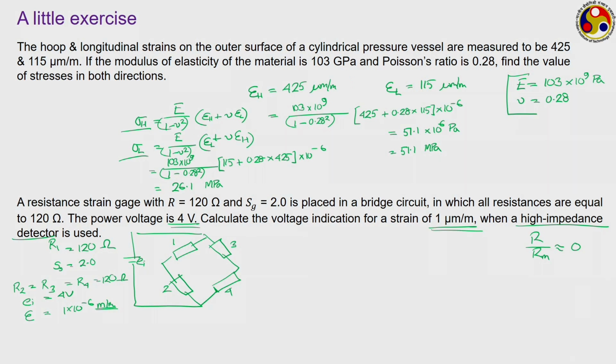For a bridge circuit, we have already done the mathematical derivation in the previous lecture, I hope you remember, and through our derivation we finally ended up somewhere here, is it not? It was delta R1 by R1 divided by 4 plus 2 into delta R1 by R1, and as per the definition of the gauge factor, epsilon g is delta R1 by R1 divided by epsilon.